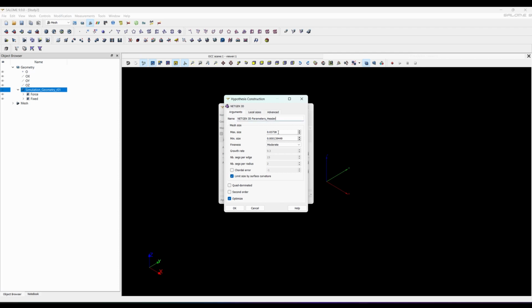By clicking on the drop-down menu for the mesh fineness, we can also control the growth rate of the mesh. This defines how quickly the mesh element size will grow as a function of distance. If we have a region of very high mesh density, we can control how fast the mesh density decreases into areas with maximum element size, i.e. low mesh density. For the maximum element size, we will use a value of 8 mm. Since the units here are in meters, we will input 0.008.